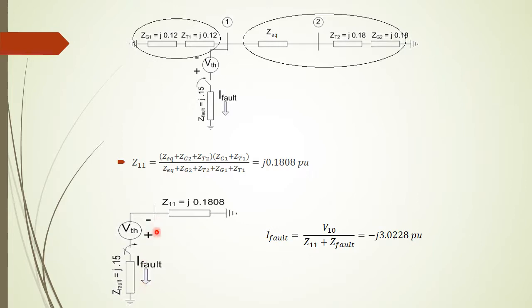Notice that when the fault current flows, the voltage on bus 1 will reduce accordingly, and we can calculate it in this case, and then using the superposition theorem we can calculate back to obtain the real bus voltage during the fault and also the other currents during the fault. Notice that we should look at our original circuit as well as our equivalent circuit.